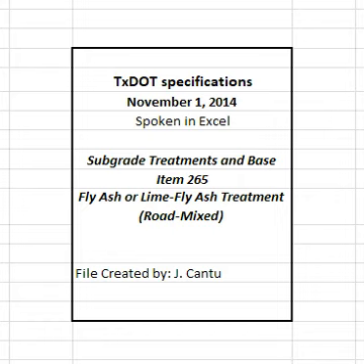2. Materials. Furnish uncontaminated materials of uniform quality that meet the requirements of the plans and specifications. Notify the engineer of proposed material sources and of changes in material sources. The engineer will verify that the specification requirements are met before the sources can be used. The engineer may sample and test project materials at any time before compaction. Changes in material suppliers may require a new mix design. Use TxDOT for material definitions.